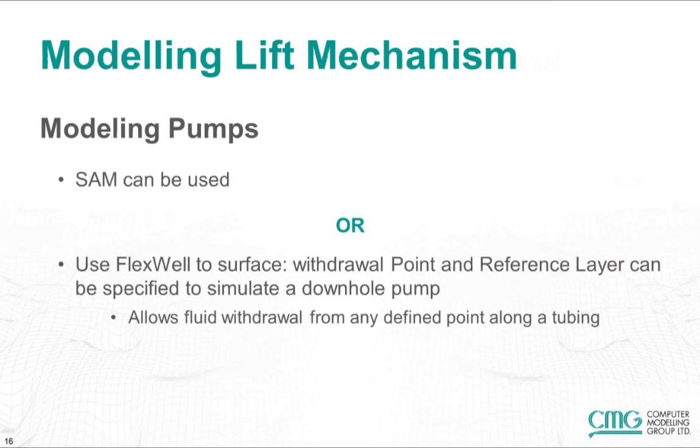Modeling lift mechanisms is another important aspect of well performance. When we come to modeling pumps, there are 2 options. We can use SAM or semi-analytical model. With SAM, we can explicitly provide the pump pressure and the pump power. The second option is to use FlexWell with a withdrawal point defined at the pump location.